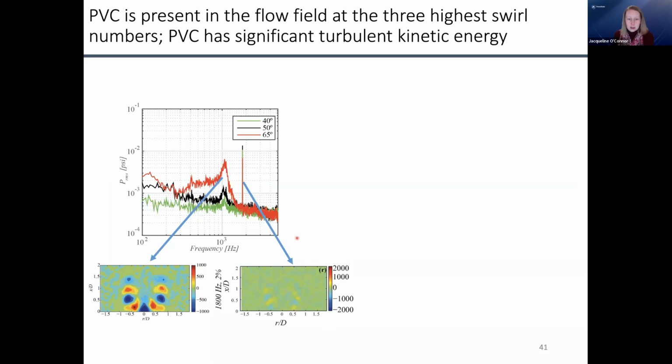And so what he showed me was the pressure spectrum from the pressure transducers inside the nozzle. He said, see, I have the acoustics on. I promise you I'm forcing it. What is this? And so when we did the Fourier transform, plotting the frequency components at these two frequencies, at the forcing frequency, this is very loud. We use police sirens to actuate this combustor. He saw basically no vorticity response, which is what I showed you in the previous slide. And then we plotted it at this peak and we saw this. And I was like, that's what's happening.